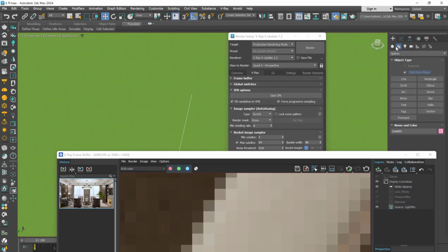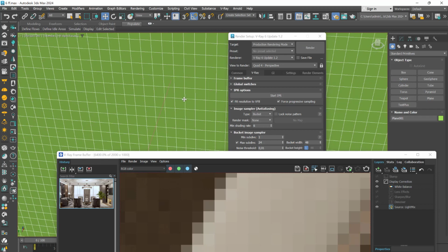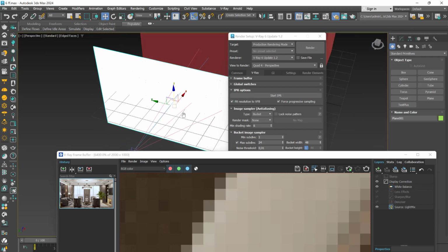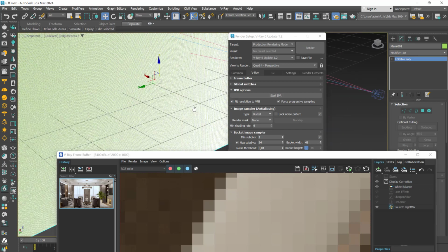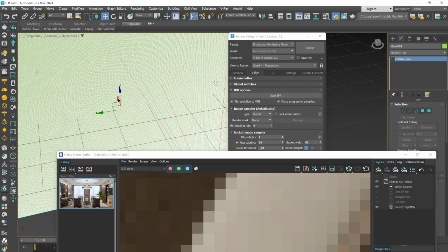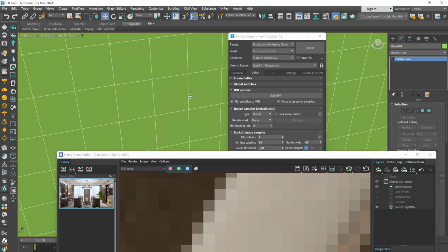First of all, I have to convert that to an editable poly, so we can create that pixel in 3D, meaning on the z-axis, otherwise I will not be able to erase our rectangle. If I used a rectangle, let's use a box instead. So I'll use a box and I'll snap.